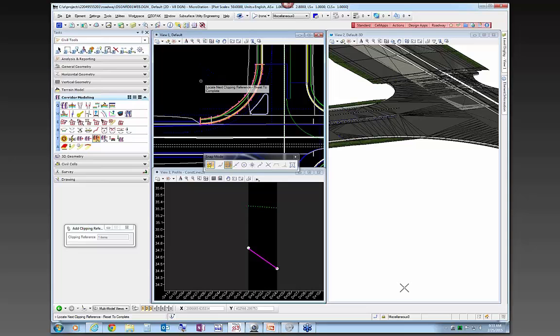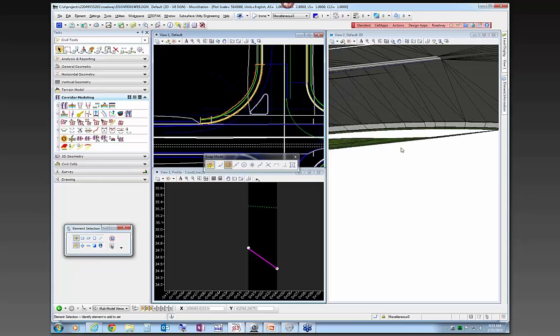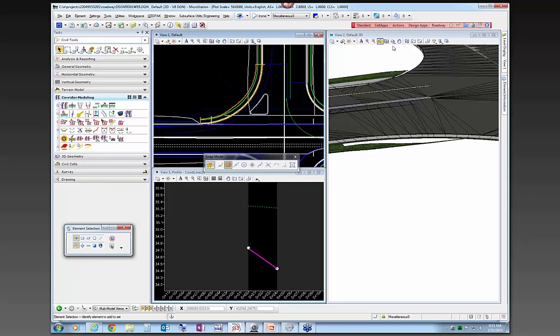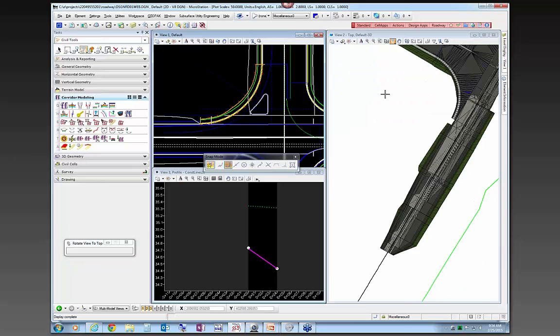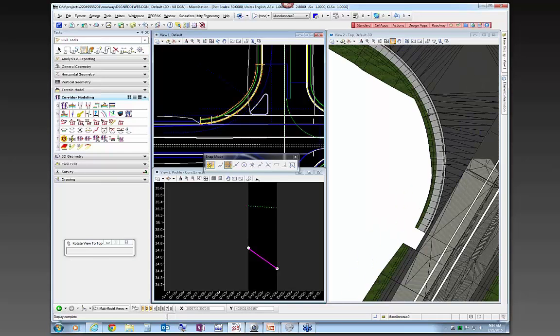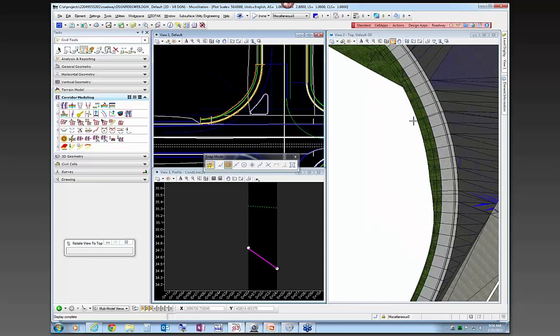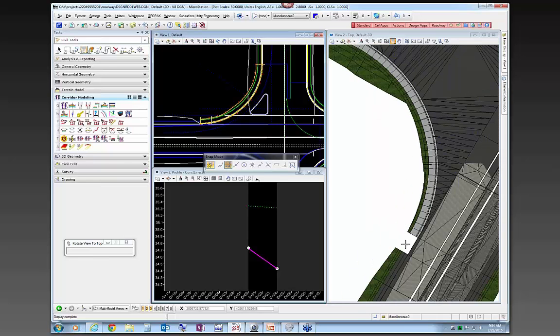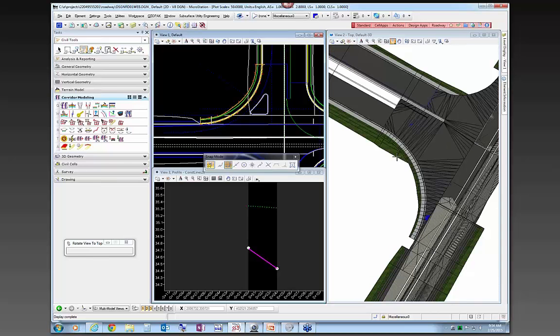And now the corridor will reprocess again, and it will clip out what was the sidewalk and buffer slope, curb, sidewalk, and buffer slope, and then it should fit in there that way. If I go to the top view, you'll see that now these things all tie together this way, and this is where I had that little gap. So I built one corner of the intersection here.